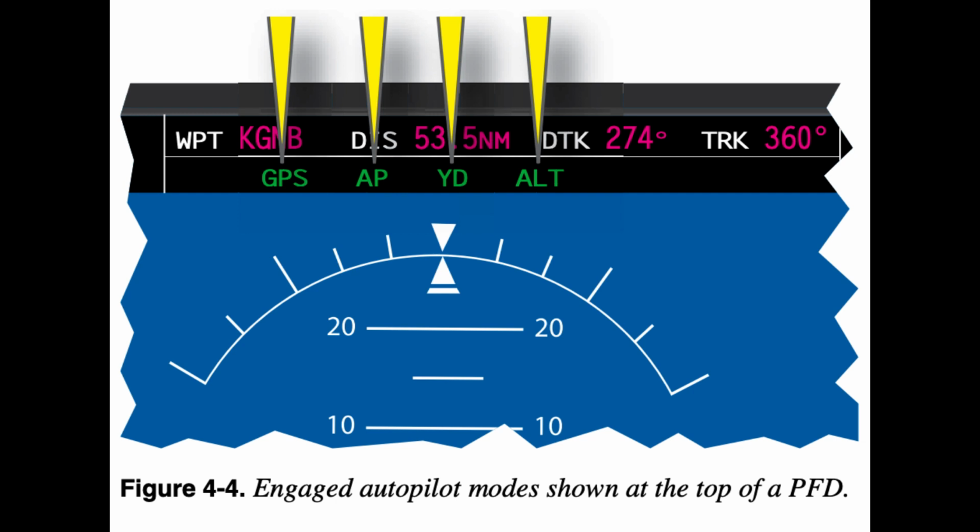How autopilot functions work. Once an autopilot mode has been engaged, the autopilot 1. Determines which control movements are required to follow the flight profile entered by the pilot, and 2. Moves the controls to affect tracking of the flight profile.